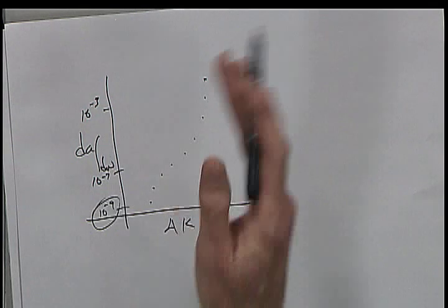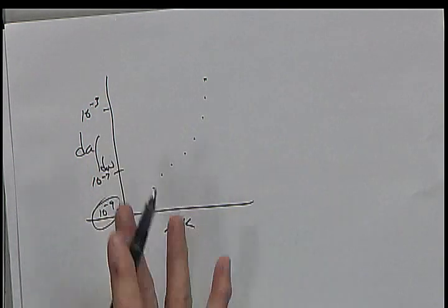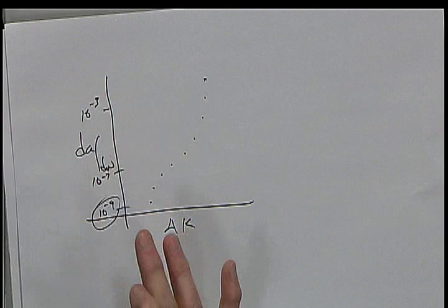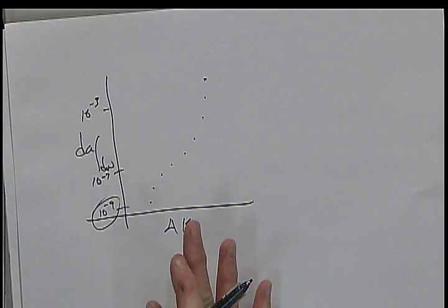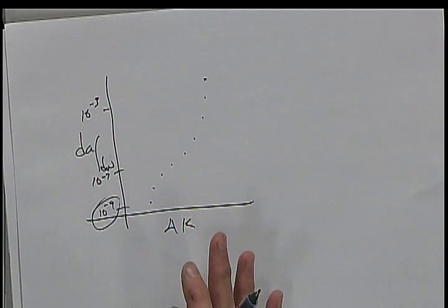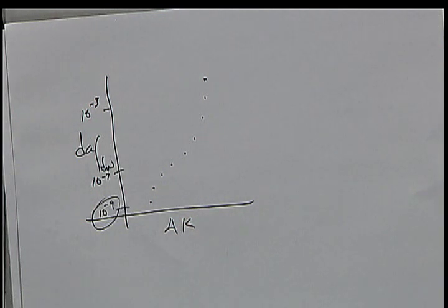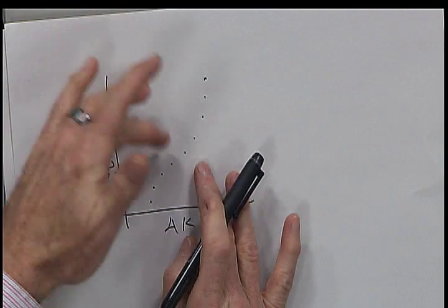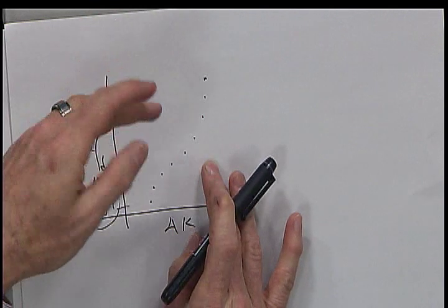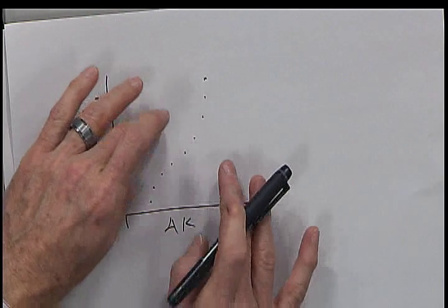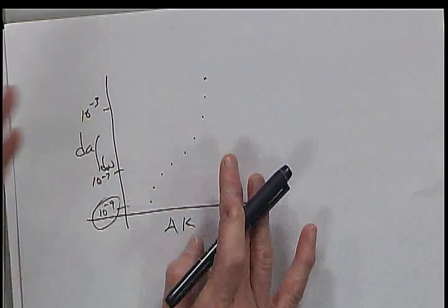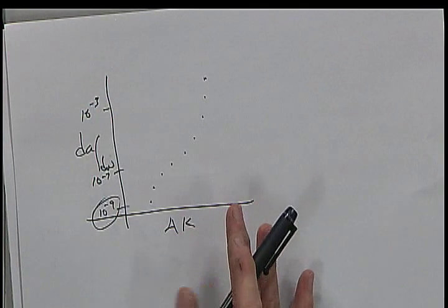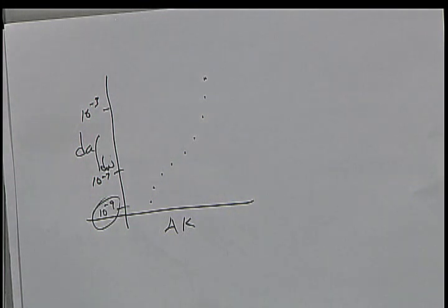So the reason I'm mentioning this is because we say we can use up to 10 different stress ratios, but if you're looking at real data, chances are you may not be able to find that many different stress ratios, right? But the point of it is, if I'm going to find out what my crack growth rate curve might be doing when I'm at some R other than the R's that I have got data for, at the minimum, how many curves would I have to even make a guess as to what the data would do?